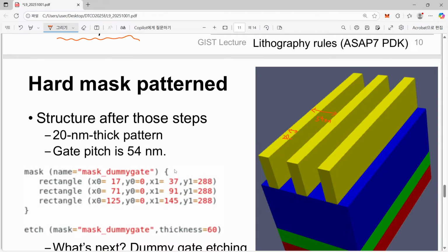One question we may have is, okay, we understand length is quite long, like 20 nanometer. And even with the state-of-the-art devices like 3 nanometer or 2 nanometer, it is not that much scaled down. So its value is around now 16, 14, around something. These are current values we are using in the state-of-the-art device. Then the natural question is, what will be the ultimate value of gate length in silicon technology?